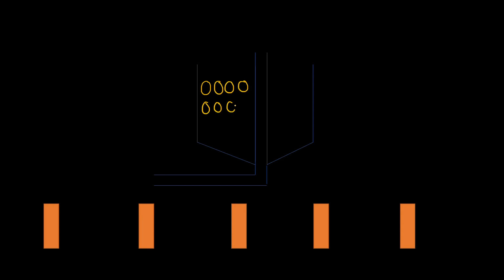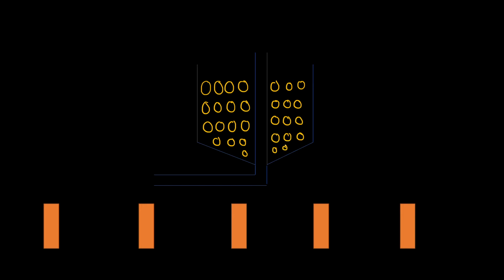The filter media may be made up of broken aggregates, broken bricks, or coarse aggregates. We cannot use very fine material in this filter media, because if the material is very fine, then it may lead to choking of the filter. So this is called the filter media.